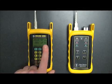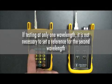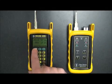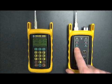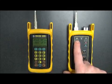Now, as you can see, it says minus 20.54. This is an okay value. Remember, we don't want to exceed minus 21. So now we're assuming we want to test 2 wavelengths, so we have to set a reference for 1300 as well. So we press F1 to move down to the 1300 wavelength. We press the lambda key to switch to 1300 nanometers. As you can see, the indicator LED is now green.